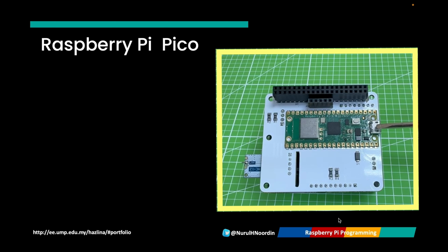The Raspberry Pi Pico does not have onboard storage like the Raspberry Pi 4. Instead, it features 2 MB of flash memory for storing firmware and programs, and USB 1.1 support, allowing users to program the board by dragging and dropping files like a USB drive. This simplicity reduces power consumption and improves execution speed for embedded systems.